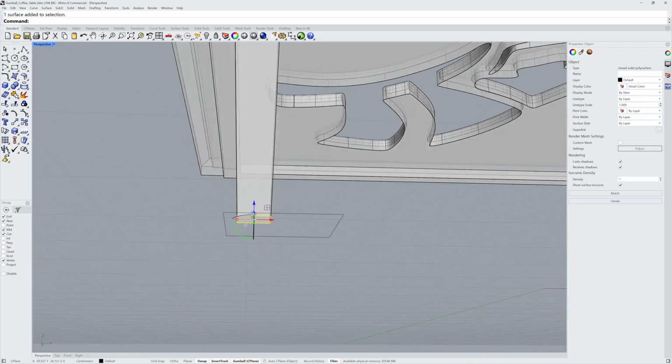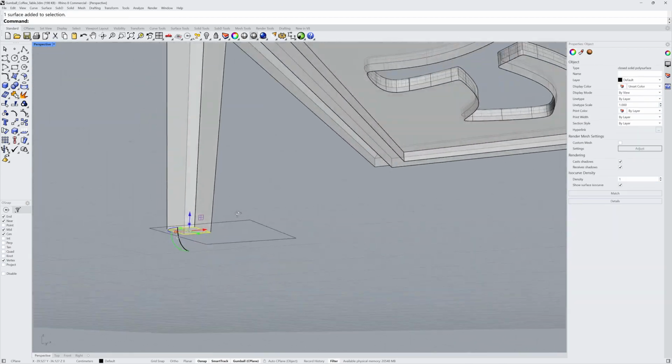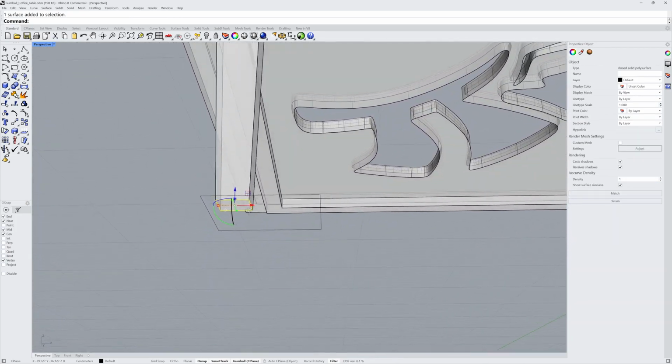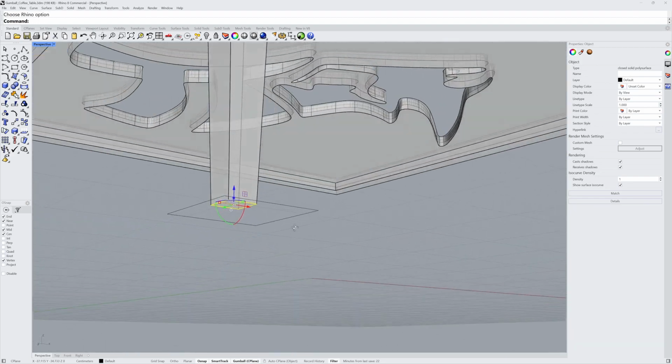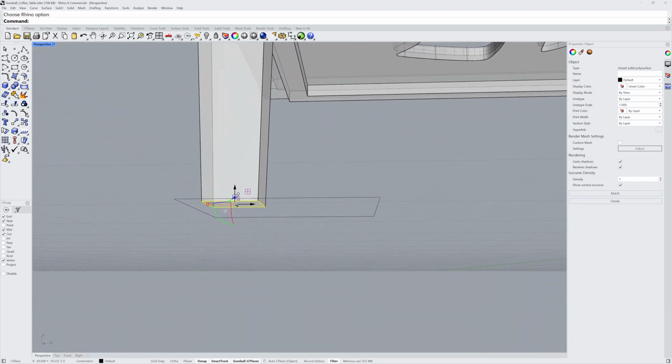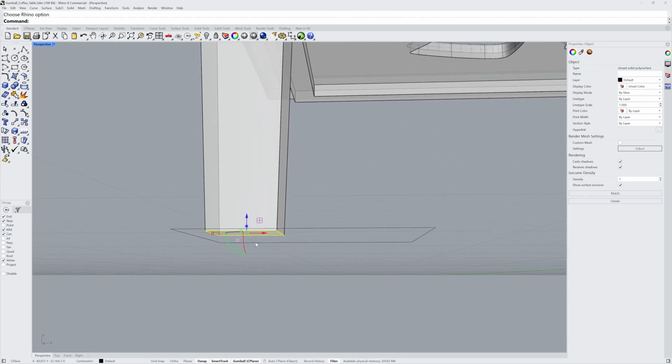This will keep the Z height of the legs the same, but scale it in the other two axes. I'll subobject select the bottom of the leg, and I want to add a foot. It's a little difficult to focus on this object though, so I'll click the settings circle and enable Rotate View around Gumball. I like this feature a lot. Every time you do a subobject, you'll be rotating around that location.